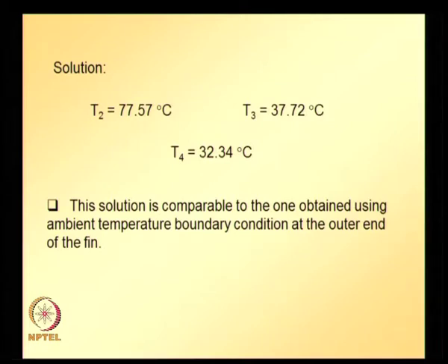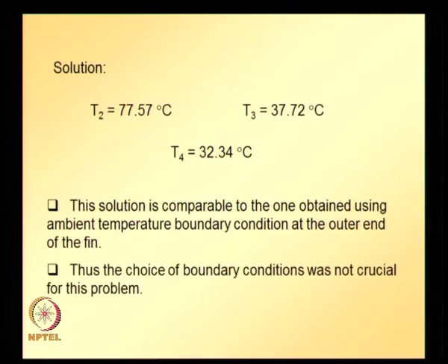Both are almost equal, thus this choice of boundary condition was not crucial for this particular problem. So, maybe in this particular case, whether you apply the convection boundary condition or the ambient temperature boundary condition, almost the same solution can be obtained.